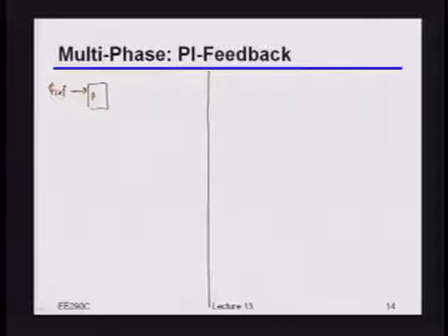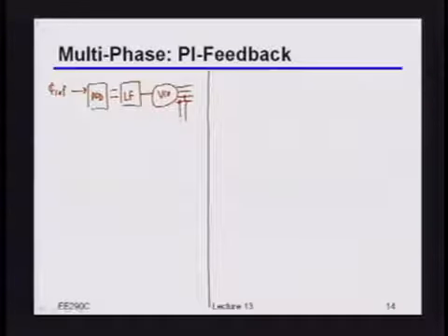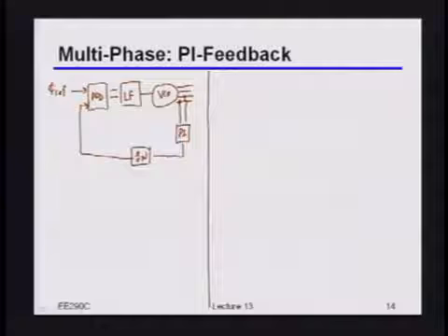We're still going to be essentially hacking things in the PLL. But this time, instead of mucking around with the charge pump itself, what we're going to do is take those multiple phases from the VCO, and this time I'm just going to put a phase interpolator. Instead of using that to directly generate the output, I'm going to use it to provide the feedback for my PLL. Where now, again, this phase interpolator is controlled by the CDR control bits. Okay?